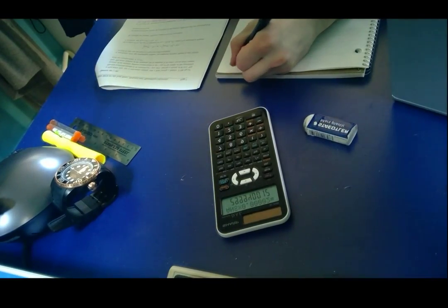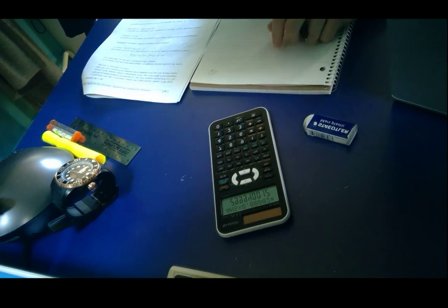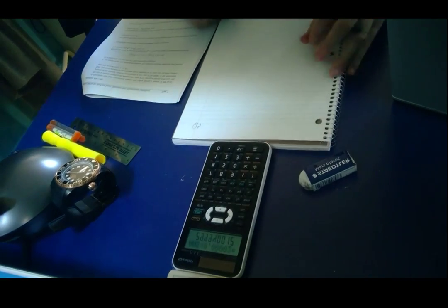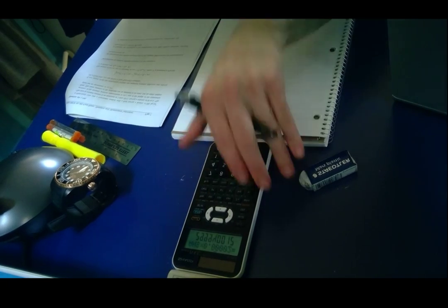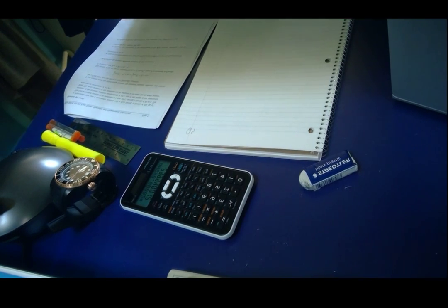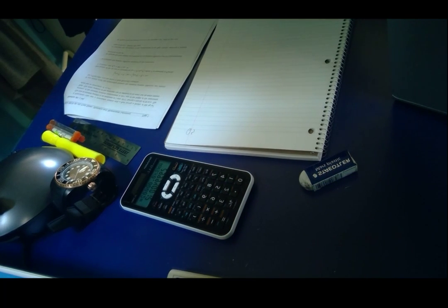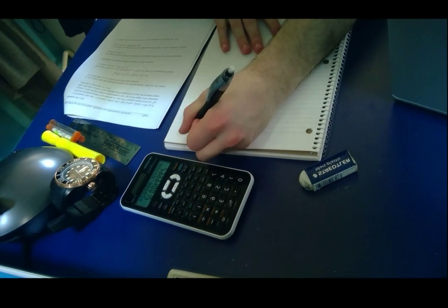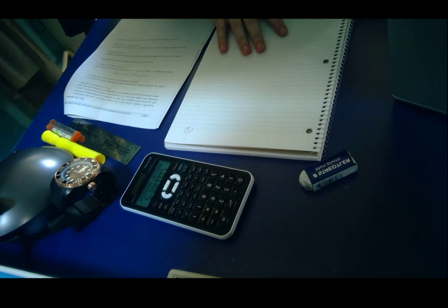Question 5 now. A pitot-static tube uses a manometer readout with a fluid having density of 820 kilograms per meter cubed. The tube is oriented parallel to an air stream at 1 atmosphere, 25 degrees Celsius, having a velocity of 30 meters per second. The accuracy of the dynamic pressure measurement is plus or minus 0.1 millimeter of the height of the manometer. I don't care about this. It's going to be used later.